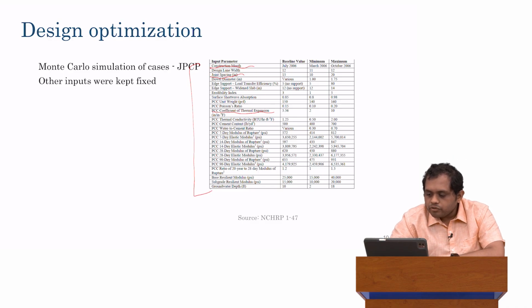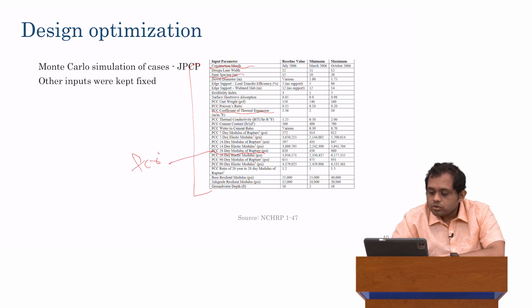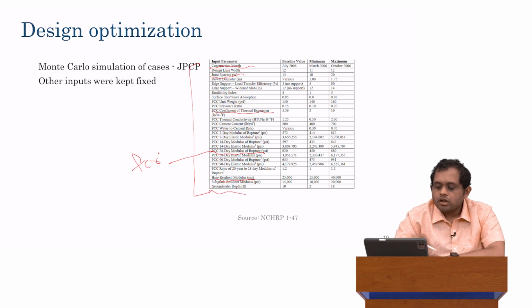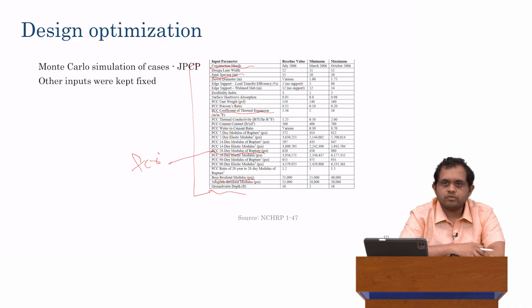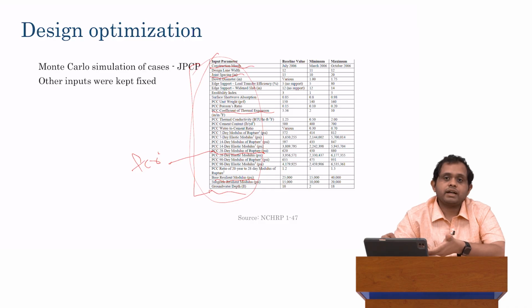Let's see, they looked at, obviously, the modulus of rupture, which we better know as the flexural strength. And then they also looked at the resilient modulus of the base. They looked at the total depth of the entire pavement, which is called the cumulative depth. And they also looked at the groundwater depth. How deep is the groundwater? Because that affects the moisture in the granular layers. We had talked about moisture considerations in a lecture on EICM. You can go back a couple of lectures and review that. So, they selected these as what they believe are the important parameters.